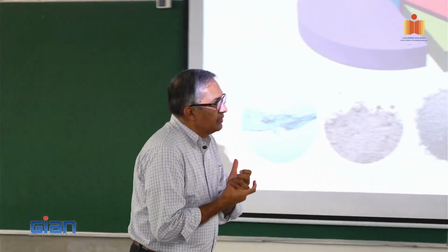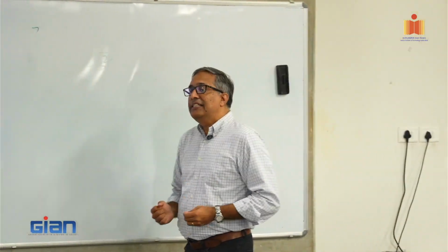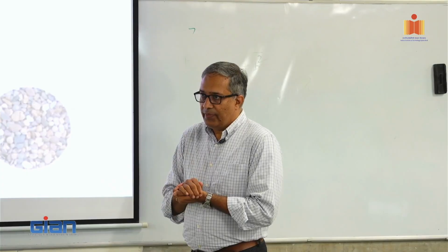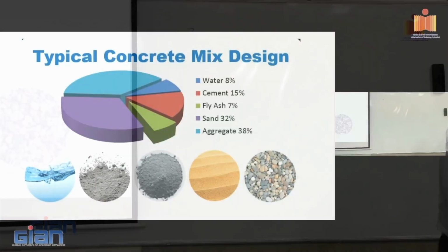Slump and yield stress relationship. Okay, fine. So you understand what the yield stress of paste is, right? At some level, we say it is that initial resistance to flow. Unless you overcome the yield stress of the paste, it's not going to flow, right?